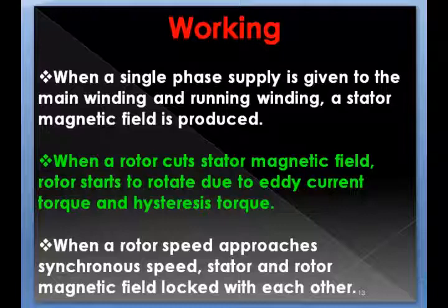According to Faraday's law of electromagnetic induction, eddy current is induced in the rotor, and the eddy current develops a torque, which is the eddy current torque. Under the influence of magnetic flux, a hysteresis torque is also produced in the rotor.